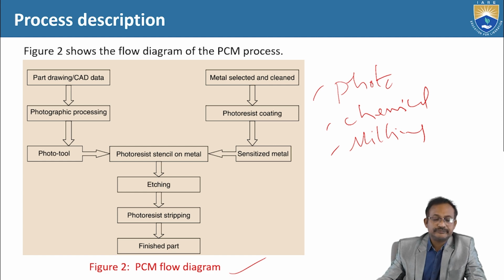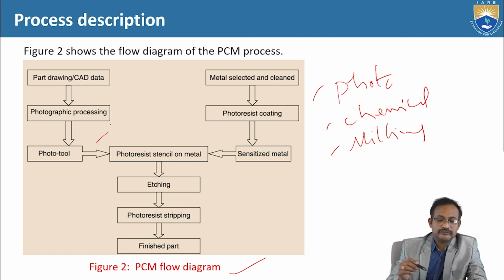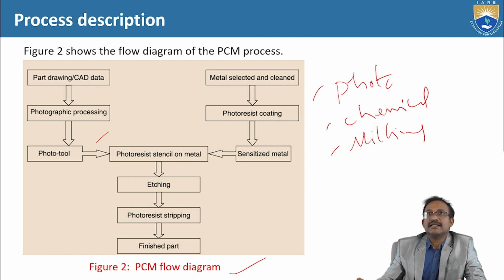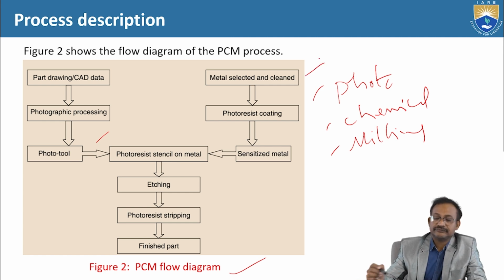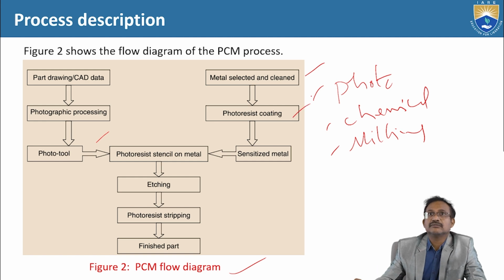Now look at this. Part drawing or CAD data, that is the input. Next, photographic processing, photo tool, and here metal selected and cleaned, photoresist coating, sensitized metal.